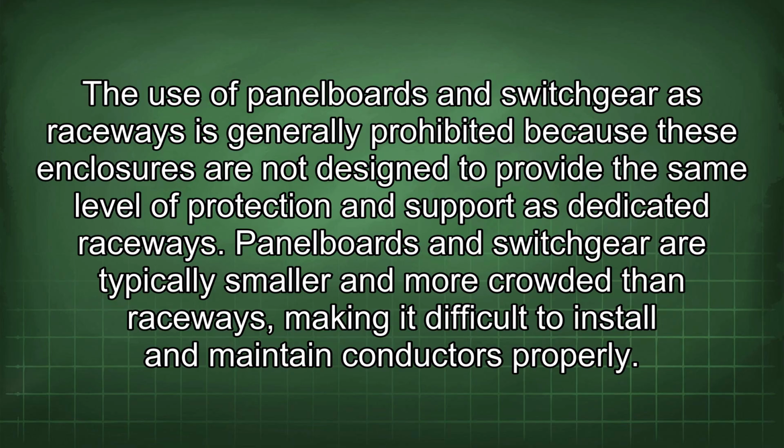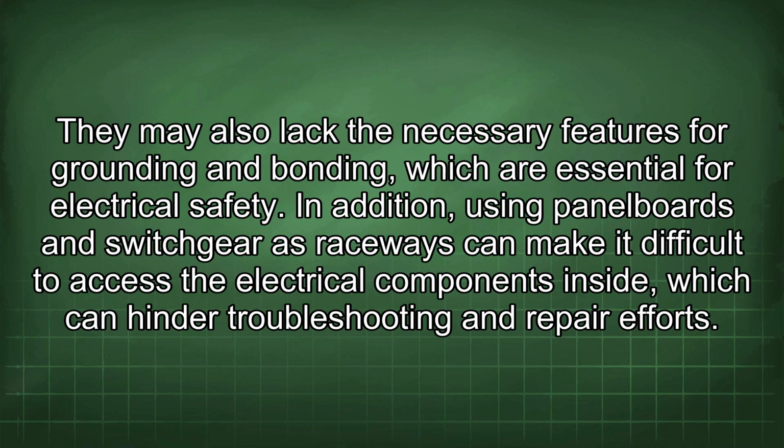The use of panel boards and switchgear as raceways is generally prohibited because these enclosures are not designed to provide the same level of protection and support as dedicated raceways. Panel boards and switchgear are typically smaller and more crowded than raceways, making it difficult to install and maintain conductors properly. They may also lack the necessary features for grounding and bonding, which are essential for electrical safety. In addition, using panel boards and switchgear as raceways can make it difficult to access the electrical components inside, which can hinder troubleshooting and repair efforts.